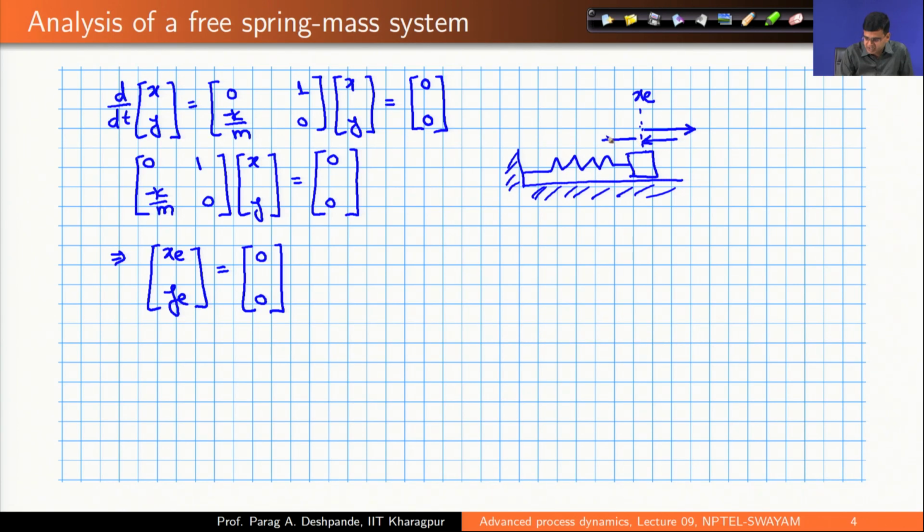I give a negative displacement, which means I compress the spring, and the system has a tendency to come back again to the equilibrium position. So, equilibrium position here means that the displacement defined with respect to this particular point, which you call the equilibrium point, is simply 0. You define that point as the equilibrium point, or you also call it unstretched, the coordinate corresponding to the unstretched length of the spring.